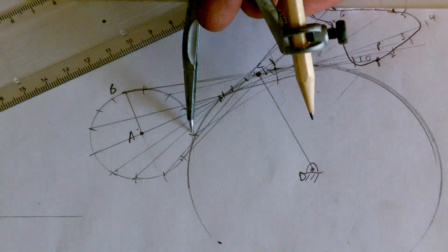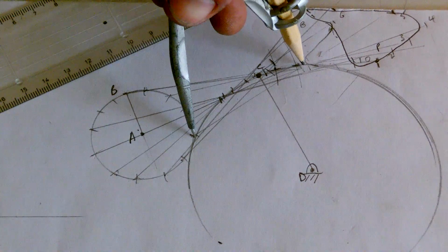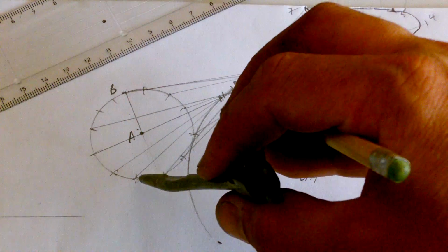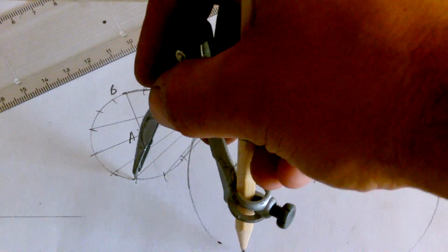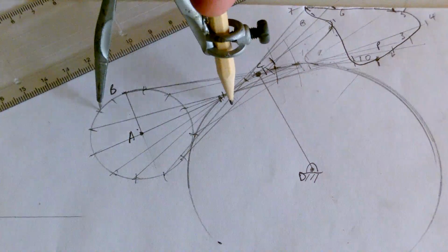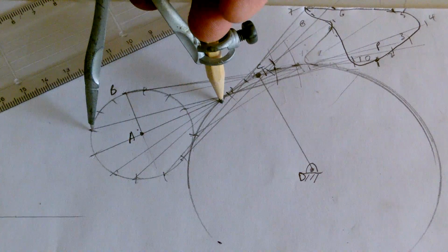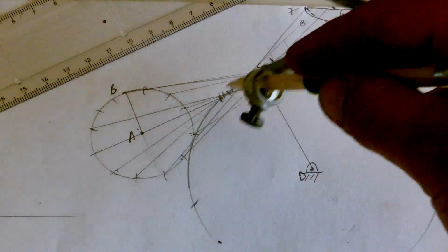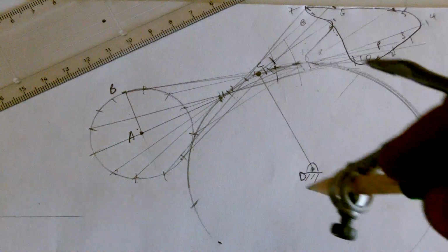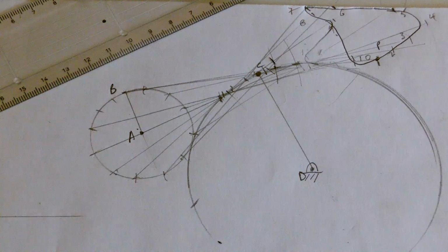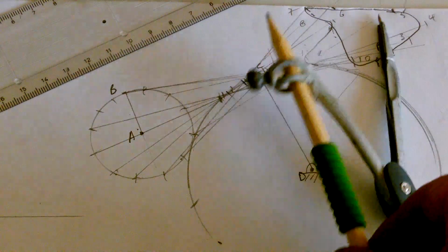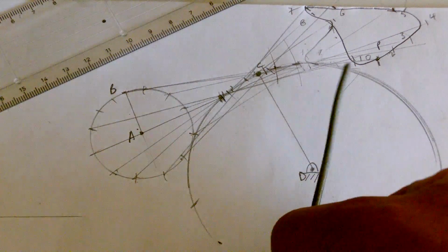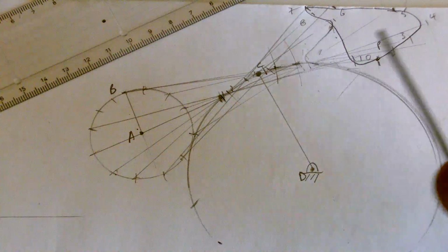Now when you're connecting from here to the arc, it can connect up here, it could connect down there as well. Each point can be marked off the circle twice. If you look at this point here, you can mark it here, and you can mark it there. Now always mark the nearest distance you were before in the previous point. And remember that since it's an oscillating arm, it's going back and then pushed, pulled and pushed to get that loop over there.